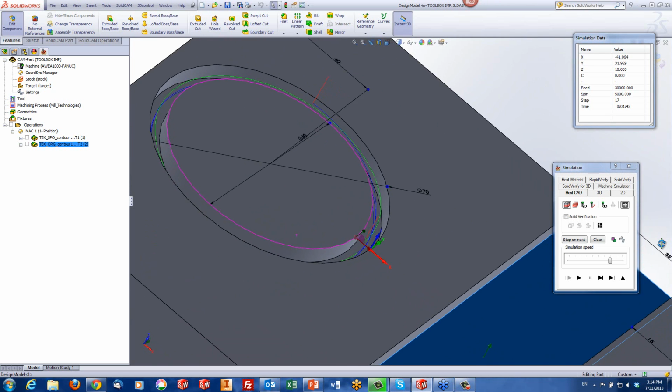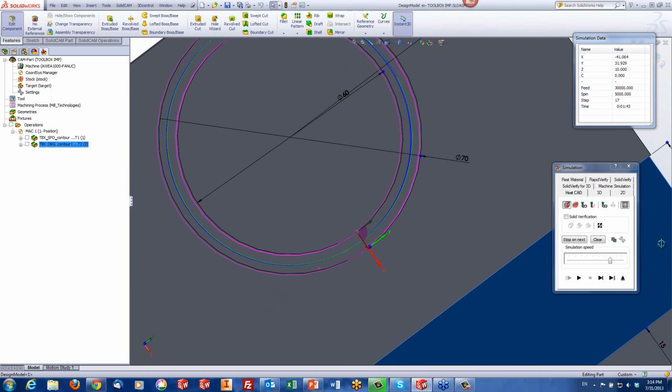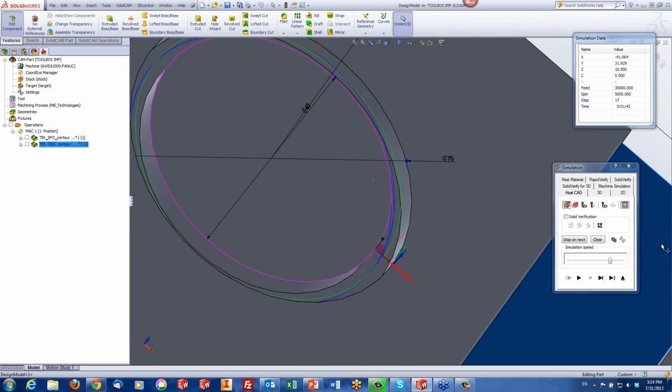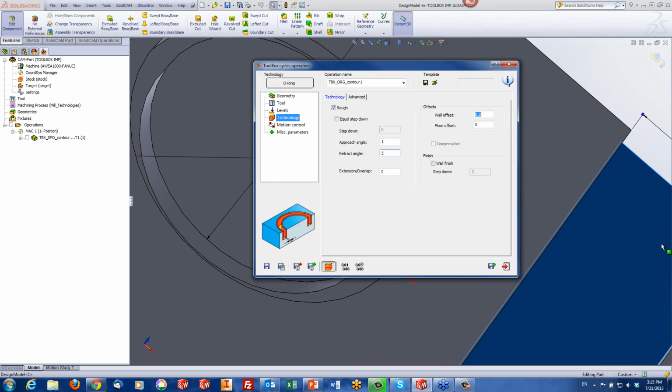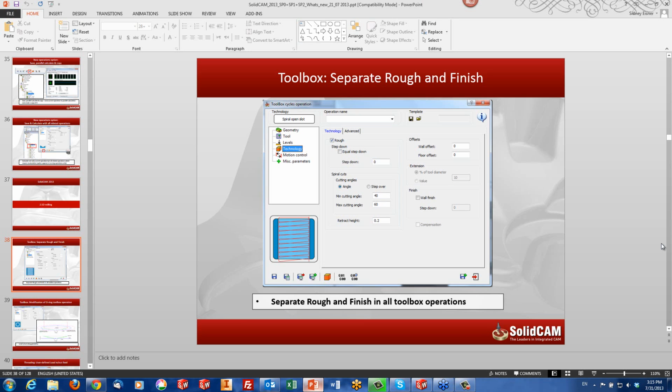Now your retreat, you'll see that your retreat actually is going up at a specific angle. Let me just catch the retreat itself. You can see the retreat over here is going up at the 5 degrees according to the shape, along the shape of the geometry itself. So we've added that inside our option of O-ring. Now, let's continue on. We'll get back to this part in a moment.